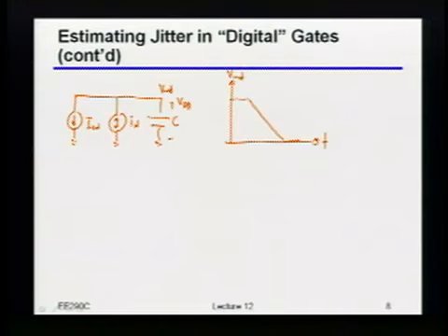Okay, so what sets that ramp rate? Ion. Yeah, it's set by ion, right? And it's set by C, right? So in other words, if I'm interested in how much time it would take me, it's something like delta V times C over ion, right? That would be, in time, how long it takes me to get from a certain point to another point where that distance is just a delta V, right? So if I asked how long it takes me to do this delta V, then of course it's just set by that. Okay, let's say this is delta T, right there. Okay?